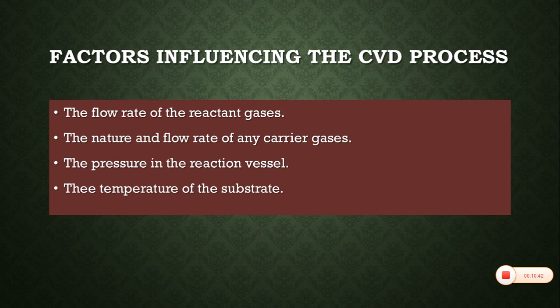Substrate heating is required in chemical vapor deposition reactors because the films are produced preferably by endothermic reactions. The temperature of the substrate influences the deposition rate and is the main factor controlling the structure of the deposit. A higher temperature yields a crystalline deposit, while a lower temperature results in an amorphous material. And a temperature which lies between the two extremes forms a polycrystalline deposit.